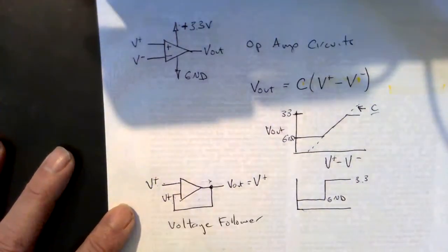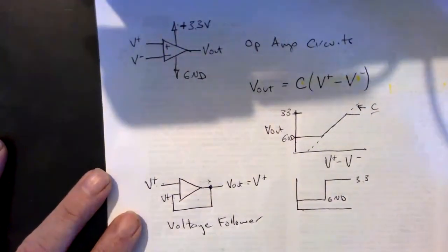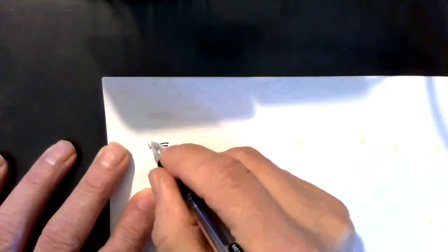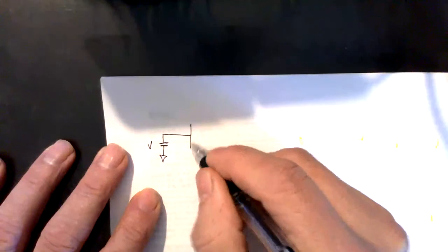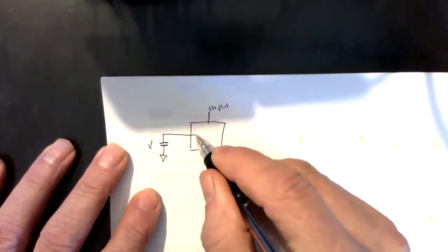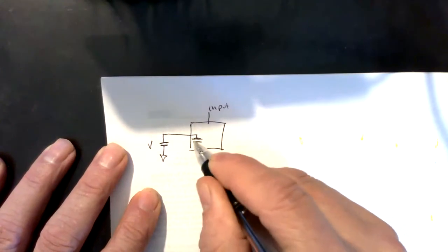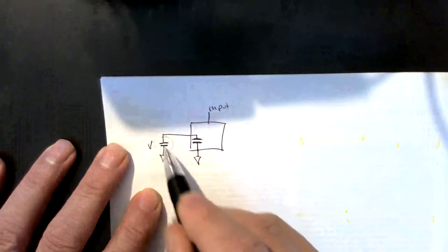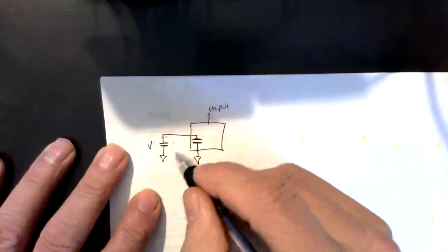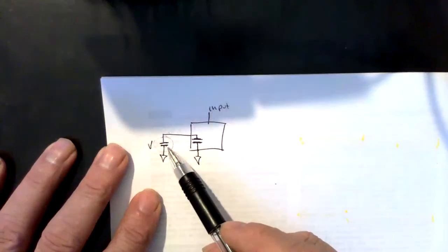Okay, so you're just getting out what you put in, and the question has to be, why would you do that, right? If you're just getting out what you put in, there doesn't seem to be a real reason for doing that. But for our spectrometer, we have a charge-coupled device, and the charge-coupled device puts a voltage onto a very small capacitor, right? And when we attach this to some circuit out here, then this circuit will probably have input voltages, and it'll have an internal capacitance, right? And if this internal capacitance is larger than the capacitance of our voltage source, then we are looking at affecting the voltage of our capacitor that we're trying to measure the voltage on, and that's not good, right?